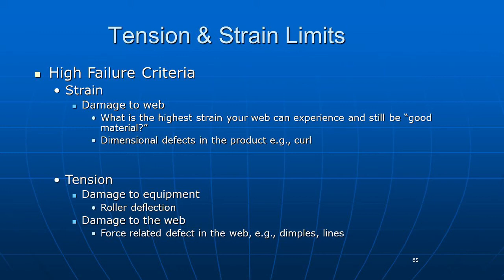Now, in some cases, you might also damage the web. If you pull your web down too hard against a grooved roller or a textured roller, you might make lines or dimples in it. And so you can create damage to your web from too much tension on some types of rollers.